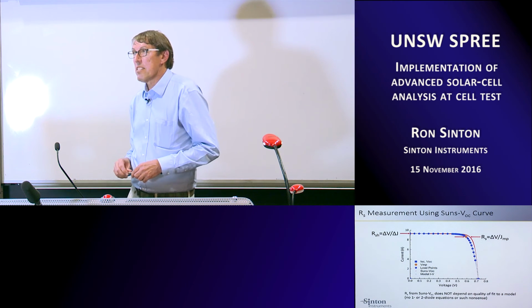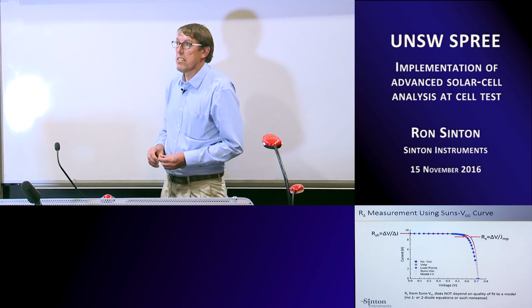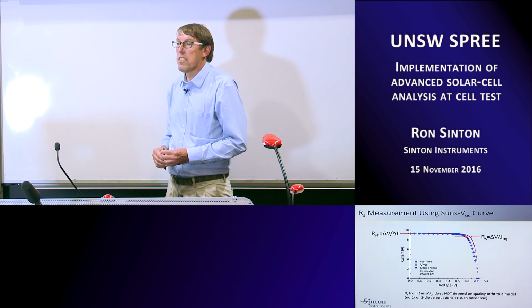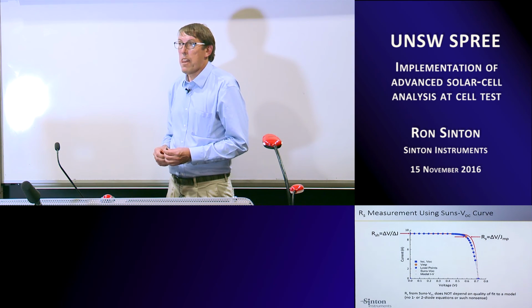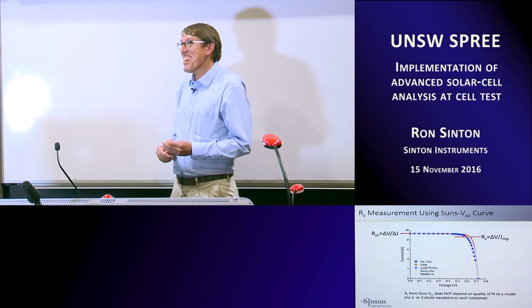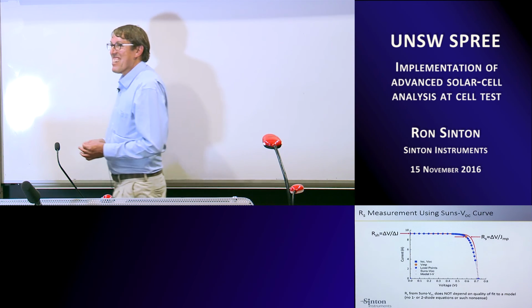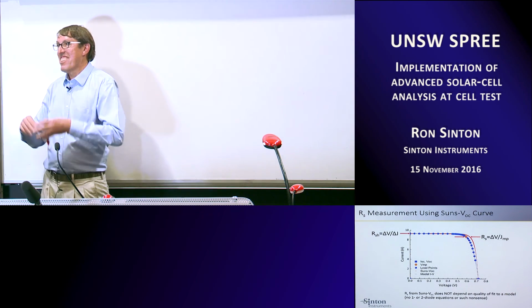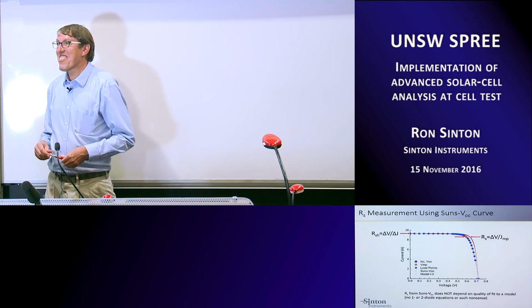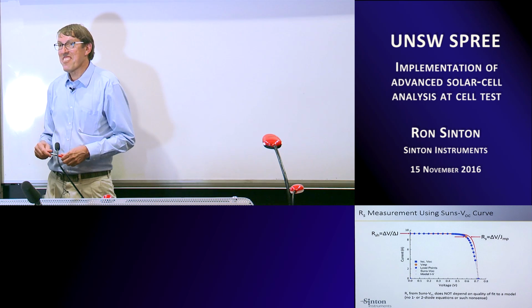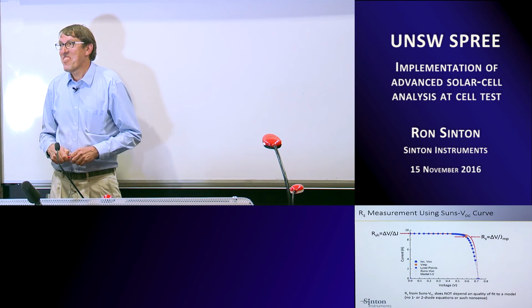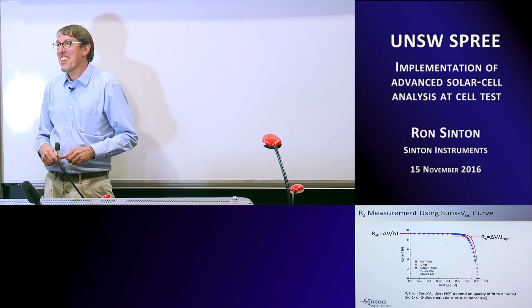Yeah, it's good because if you can completely decouple that RS reliably from your voltage, then you can make a lot better inferences on what that RS means, and it's much more useful. Yeah, I mean, this is power loss. When you try and figure out what it means, now that's something else, because it can be transport losses, carrier density gradients in the cell. It can be all sorts of things that aren't related to the electric field.